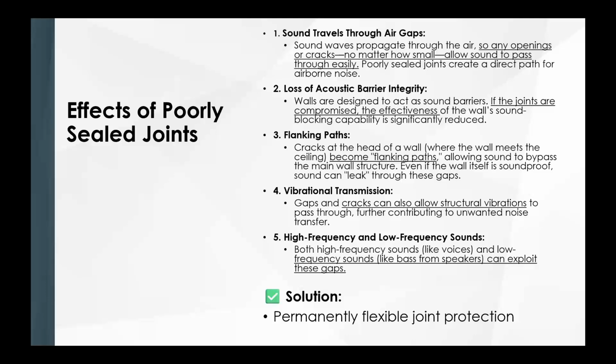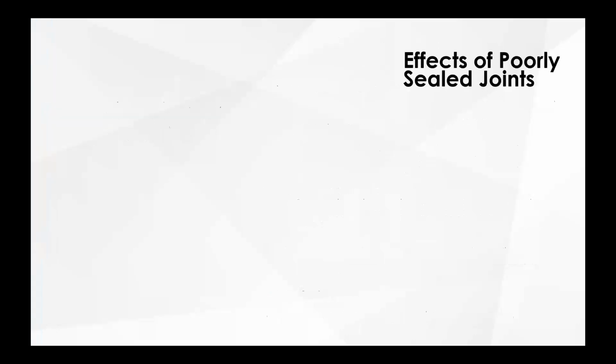You'll hear some sound consultants call that out. I've seen it a lot in specs where they'll say permanently flexible sealant. There are some permanently flexible sealants out there that, literally months later, a year later, you could press on it. It's still very flexible. The only thing that I caution you on, if the wall is also fire rated, permanently flexible sealants aren't known for being fire rated. They're just sound rated.